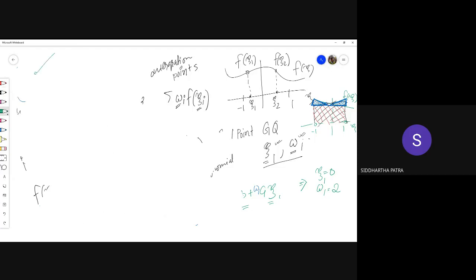Let's just stick to the four noded quad element. I'm not going for higher order elements. Even if the four noded quad element were a parabola, B transpose dB would be quadratic functions. Each term in this product should be quadratic in xi and eta, even if the determinant of J is a constant. Even in the simplest situation where the Jacobian is a constant, this is still quadratic in xi and eta.